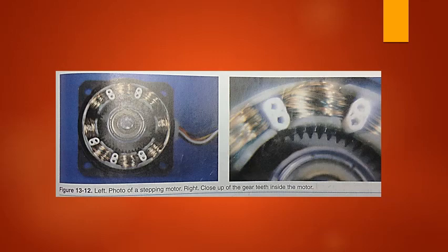Stepping motor. The stepping motors derive their name from the fact that they rotate in steps or small angles, one by one. Figure 13-12. Notice that the stepper rotor resembles a gear. It has teeth around its entire circumference, and it is usually magnetic. The stator consists of a gear-like structure with windings embedded in a pattern of two-phase, three-phase, or four-phase. The windings receive pulses of power rather than continuous application of power. The number of pulses applied to the stator windings determines the distance of travel the rotor makes.